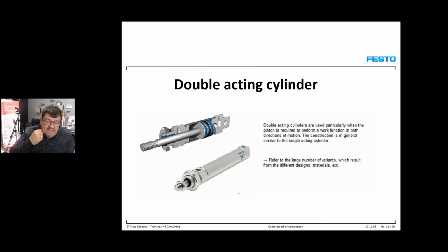Therefore, there is a large number of variations: different sizes, different looks, and different materials used to manufacture double acting cylinders. It's also important to understand the materials. And you can ask yourself, what are the criteria when you select cylinders? Like we mentioned in the basic pneumatics course or webinar, we talk about force, speed, stroke length, position, angle, sensitivity, whether safety is involved, and controllability, and a lot of other things that are important when selecting what type of cylinder must be used for which application.